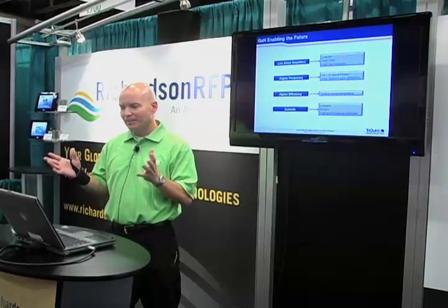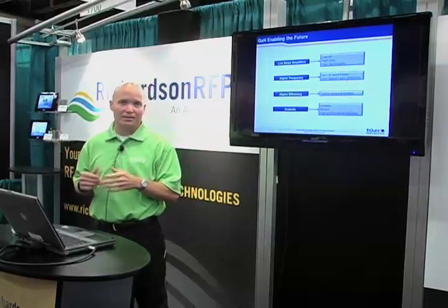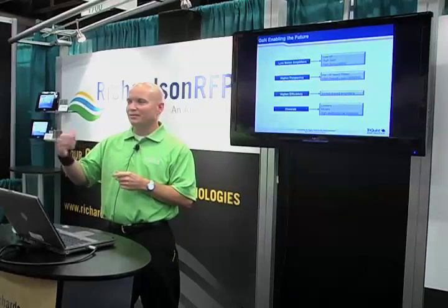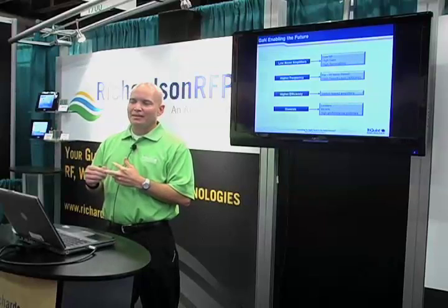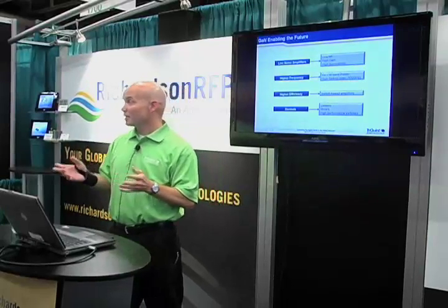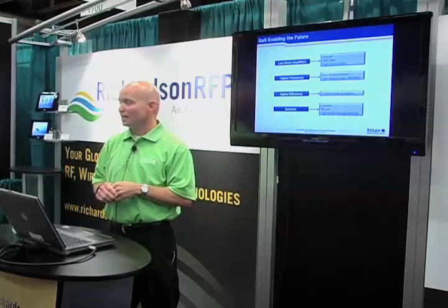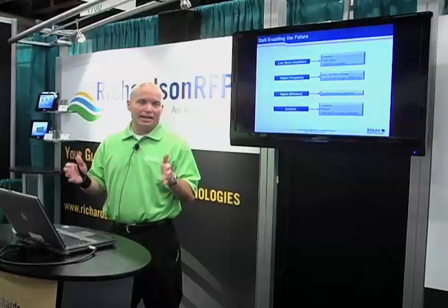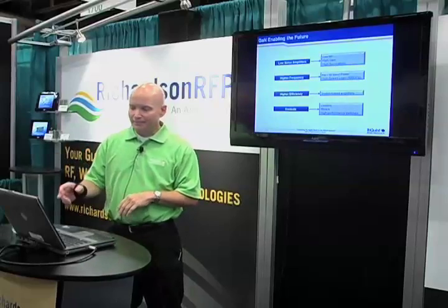So that's where a lot of the benefit is for the low noise amplifiers. But again, our 0.15 process that we're developing now is achieving as good or better noise figure than our gallium arsenide 0.15 process, which was world class. So really, we're real excited by the LNA potential for gallium nitride.